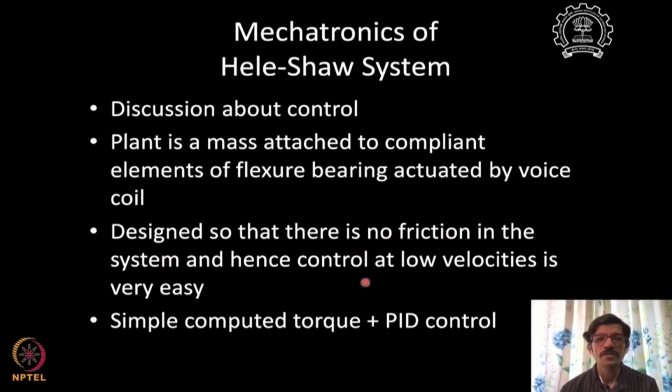Okay, the fluid is giving some friction, but that fluid friction force is usually a viscous friction force. Okay, it's not a Coulomb friction kind of force. So that's why you will not find stick behavior offered because of the presence of the fluid. And we are avoiding the stick-slip behavior because of two solid components rubbing against each other. That kind of Coulomb friction we are avoiding by using compliant mechanisms in the design.